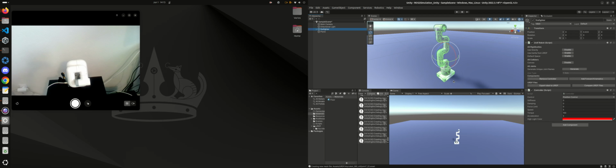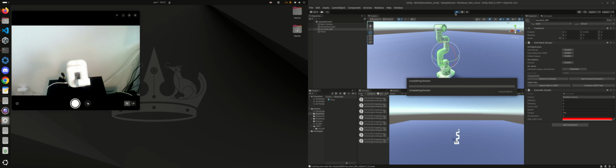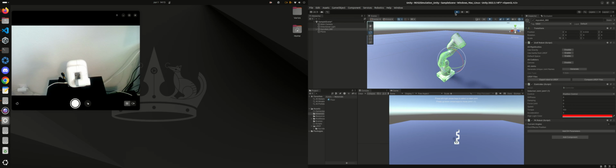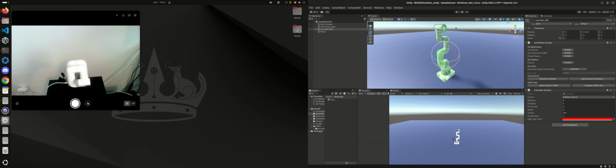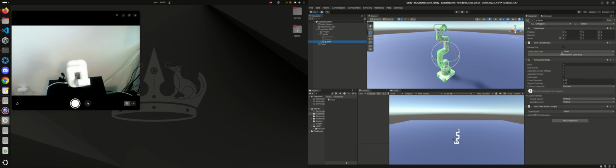Double click on our robot, change the name to MyCobot 280. Okay. Now hit play, and we have a problem. What is the problem? The base, as it needs to, doesn't move. It's really important. To solve this problem, just go to the base, and then we need to tick it's a base link and immovable.